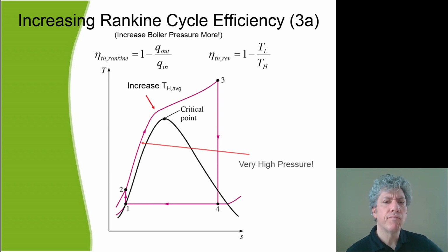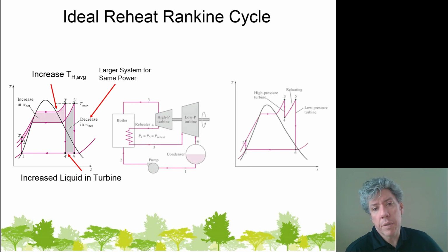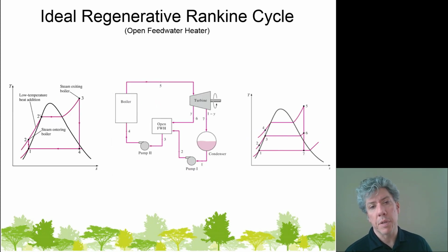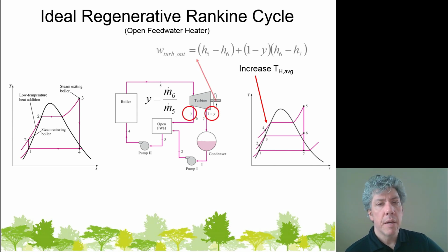Well, let's see. Essentially what we're doing is we're increasing the temperature at which we're adding thermal energy, right? We're not doing anything about state 2. Notice the temperature goes up until it reaches the saturation line along the process curve, remains at constant temperature as it boils off, and then from the saturated vapor line moves up to either state 3 or state 3 prime.